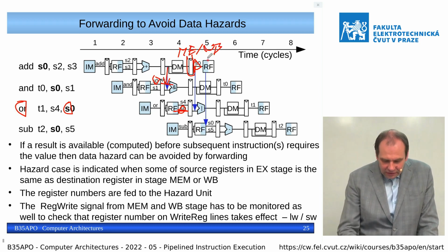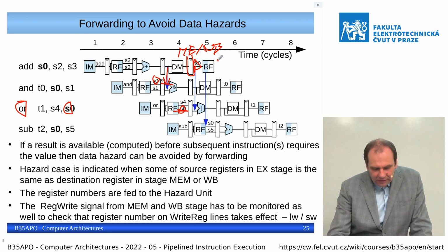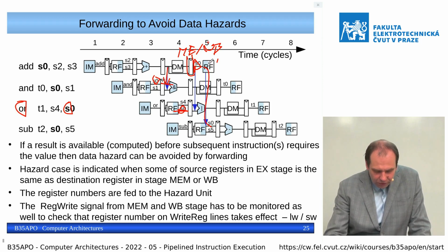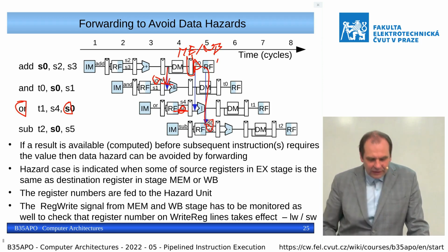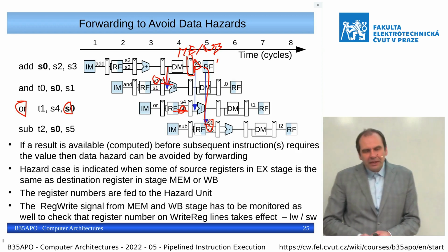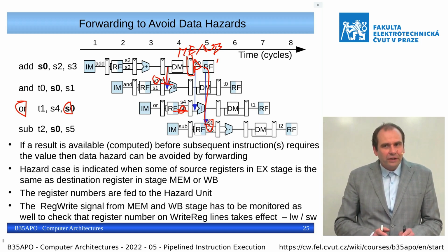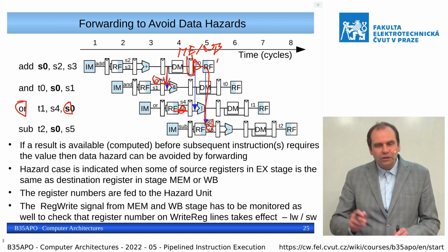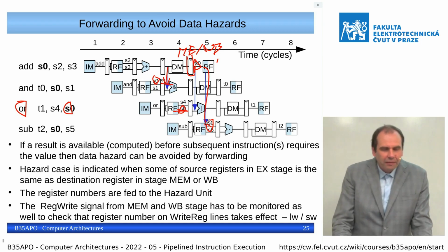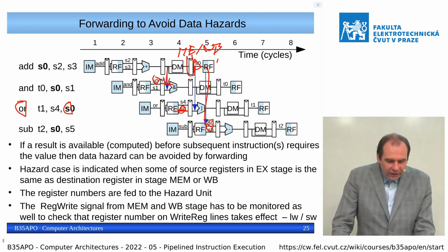And at the end of this clock cycle, the value is already available in the registers. And if we read the value during the 5th clock cycle from the register file, then there is a mechanism so that we already get the correct value. We can imagine that, writing and reading from the register file, for example, we do not finish writing at the rising edge of a given clock cycle, but that we finish the writing at the falling edge.